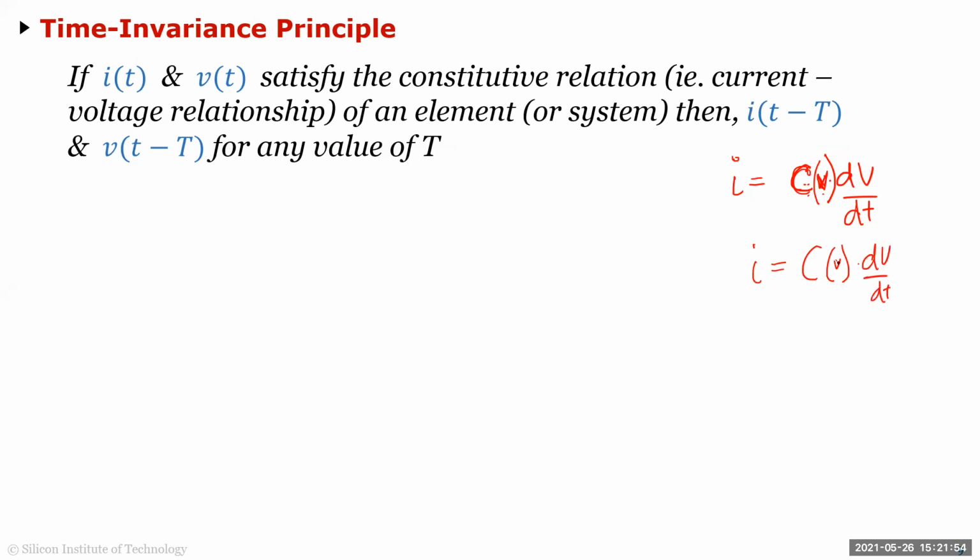If that's the case, then I1 plus I2 is not equal to the sum, because you can't say that it is C of V1 times d(V1 plus V2)/dt, or some X value, because you're trying to say that C is constant. If that were the case, then this should be valid, but it is not. It is a function of V, so then you can't use it, right?